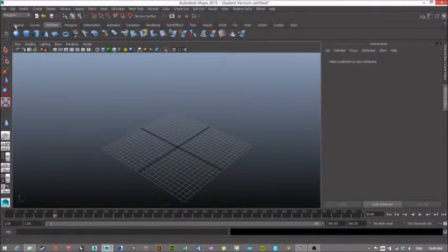All right, blend shapes. A blend shape is where you take two topologically similar volumes, surfaces, objects, and you can actually blend between them. If you remember at the beginning of that video, there is a cube, and that cube got all kind of weird and deformed and looked awesome. I'm going to guess that that person took a cube into Mudbox, subdivided it out so that they start with a cube with a really, really high face count, did all their modeling and sculpting on it, and then exported both the original cube and the deformed cube, and then all you do is you create a blend shape, which we'll do right now.